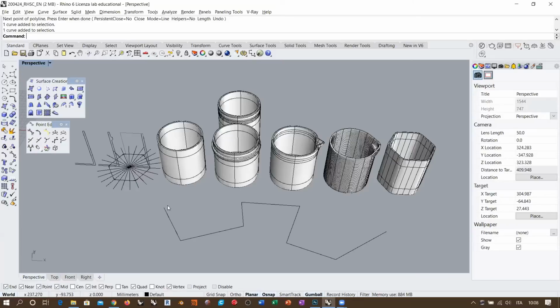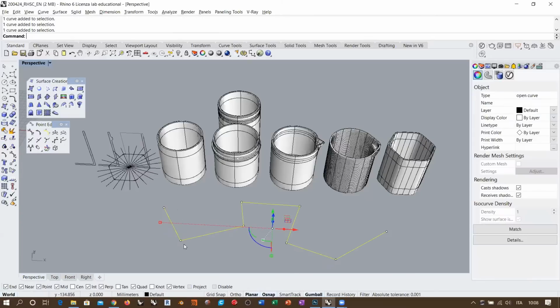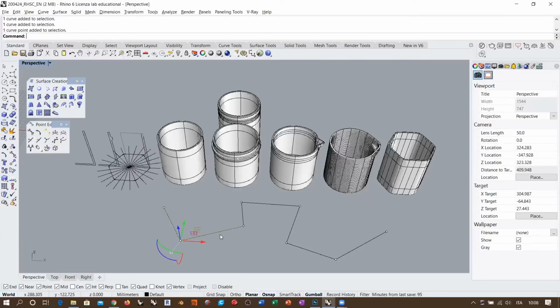They are all full multiplicity knots. So in that case, each knot produces a kink, which is a vertex. So in the polyline, these discontinuities are at the same time control points, and they are also knots, and they are kinks. So the polyline is an extremely particular NURBS curve because of this particular situation.